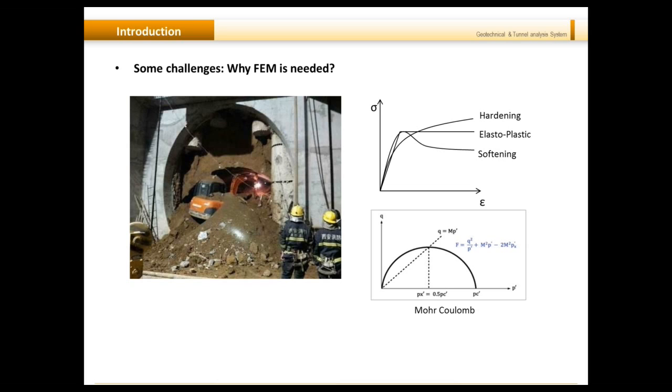Then you should definitely go back and reevaluate those designs. So even before the construction goes out in the field, you should simulate the construction sequence and see, if we have removed this much stress from the system, what the deformation would be. So basically, soft pockets and faults need appropriate constitutive material models and interface controls.